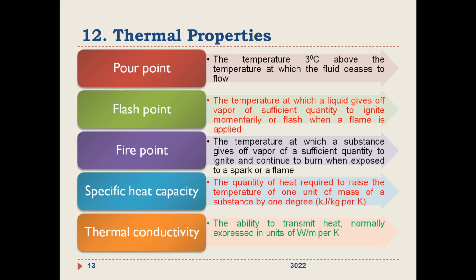Fire point: the temperature at which a substance gives off vapor of sufficient quantity to ignite and continue to burn. So you should understand the difference between flash point and fire point. Flash point is momentary ignition. It will just ignite or flash, but it will not continuously burn when the temperature reaches the flash point. But it will continue to burn when the temperature reaches the fire point.